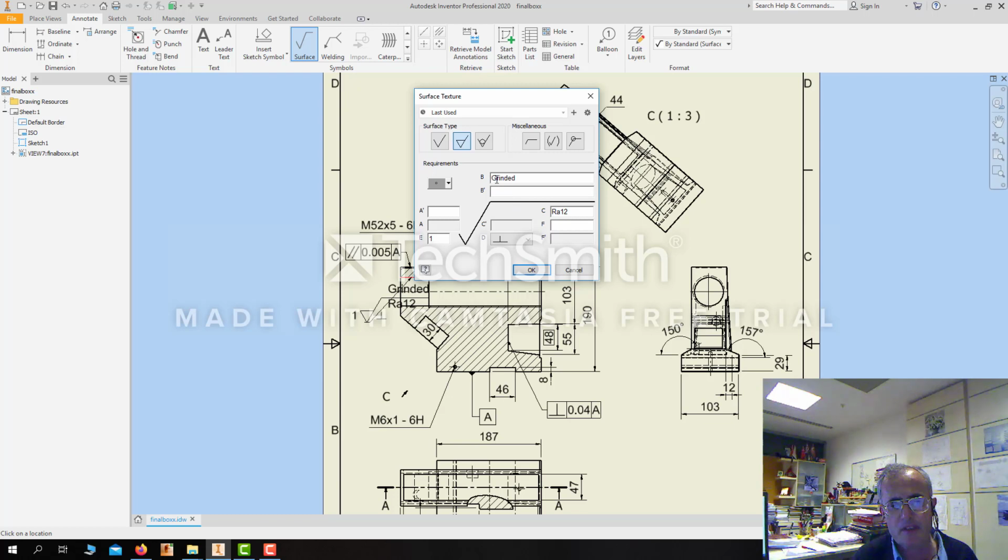Into such a box we write the common name of the finishing process using the past participle tense. Okay. But in the new version of the standard, this place is used to write the roughness value. Here in the old version we use this box to write the sampling length, roughness with cutoff value.